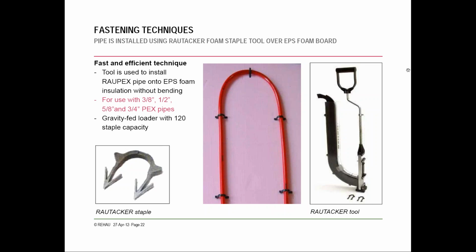Now, some of the newer techniques definitely help speed up installation time. Depending on how big your area is, you may be looking at these, or if you're doing a lot of these, they certainly help cut down time and cost. This is probably the most common one that you've seen or heard of, where they're just installing these foam plastic clips into the foam board. So obviously this would be assuming you're using rigid insulation underneath, and depending on the size of the pipe, you can use different sizes to install it.